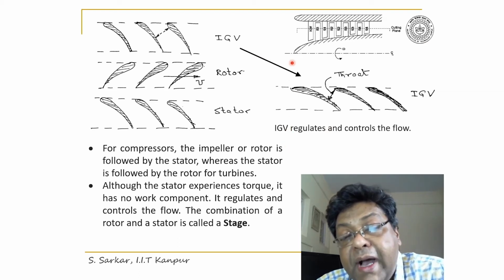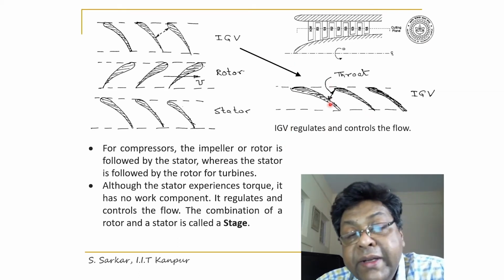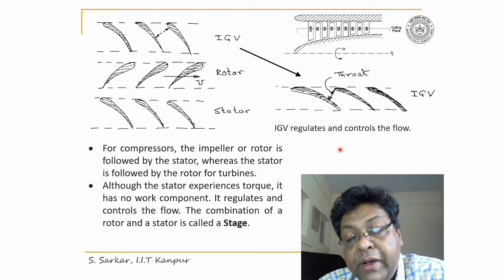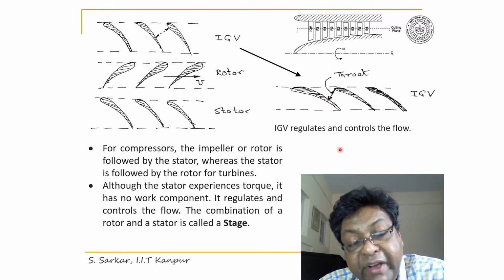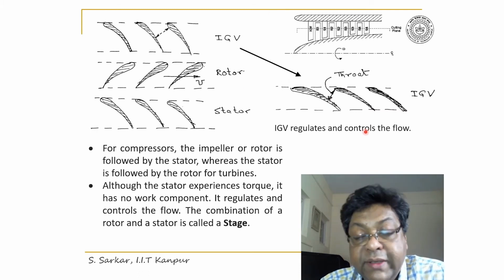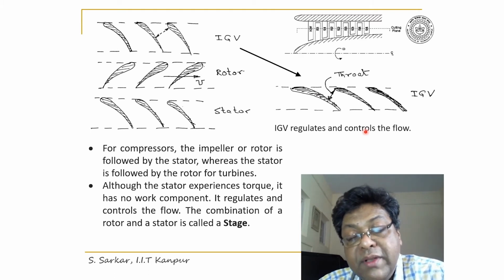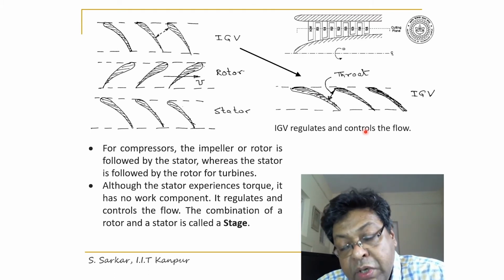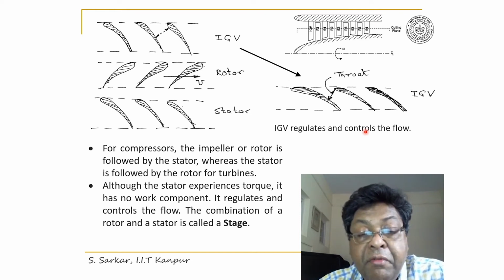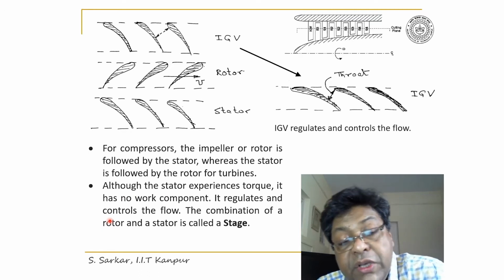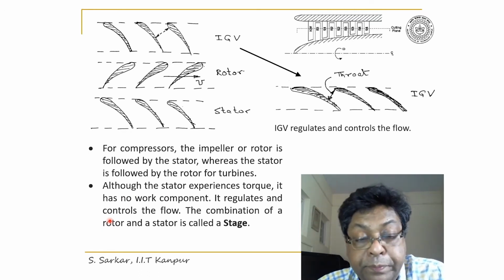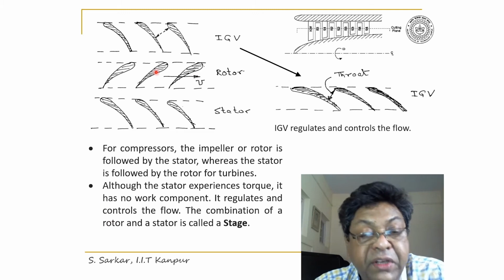By tilting the IGV, I can increase or decrease the effective area through which the fluid passes, and thus I can control the mass flow rate. So the function of IGV is to control the flow,